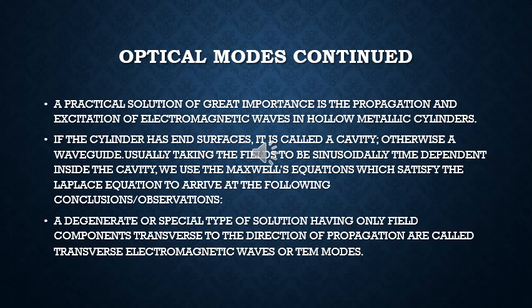Continuing with the discussion on optical modes, a practical solution of great importance is the propagation and excitation of electromagnetic waves in hollow metallic cylinders. If the cylinder has end surfaces, it is called a cavity. Otherwise, a waveguide. Usually taking the fields to be sinusoidally time-dependent inside the cavity, we use Maxwell's equations, which satisfy the Laplace equation, to arrive at the following observations. A degenerate or special type of solution having only field components transverse to the direction of propagation are called transverse electromagnetic waves, or TEM modes.